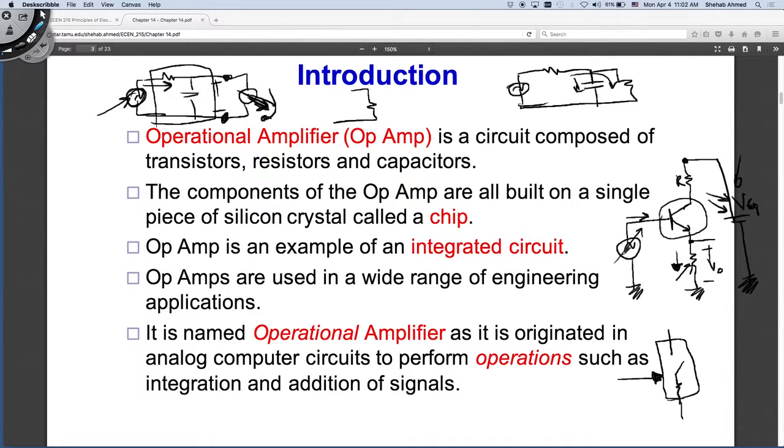It means that once my sensor tells the control, the brain of the transistor, that I want to start providing some value of current, this resistor here internally will be variable as well. So it's like a switch with a variable resistance in series. This is what the transistor looks like: a controlled switch with a variable resistance in series.